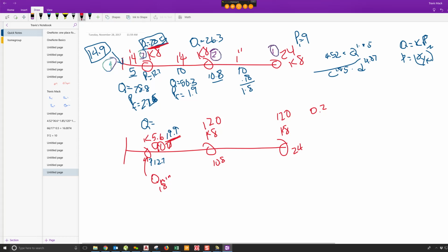So what that's doing is you're basically trying to throttle down the system, and NFPA, because this can get real confusing as far as maintenance and stuff goes, is say you got a big open warehouse or a big open room, you got heads here, here, and here. You got a K8, a K8, a 5.6, and a 4.2 because you're trying to balance down the flows with your K factor. NFPA 13 says you can't do this because what's going to happen when the building changes hands 2 or 3 times and this head has got to be replaced, they're going to get the wrong head in it, or they put a 4.2 instead of a 5.6 here. Things aren't going to work.